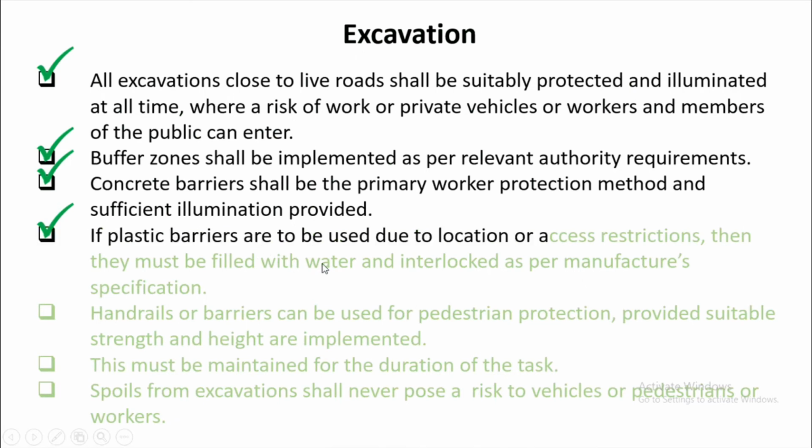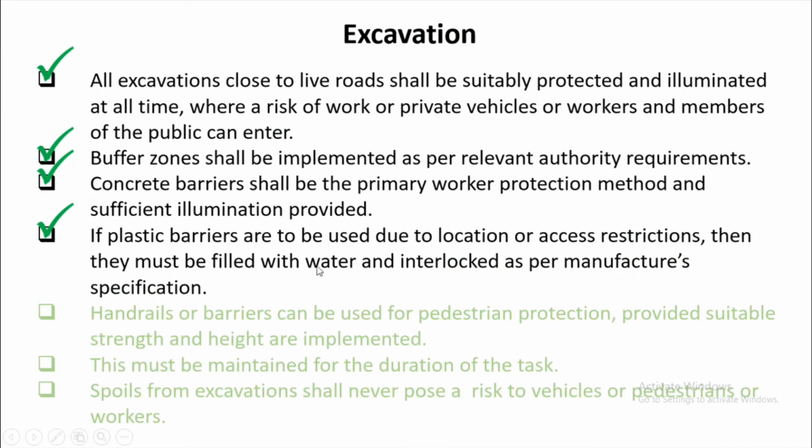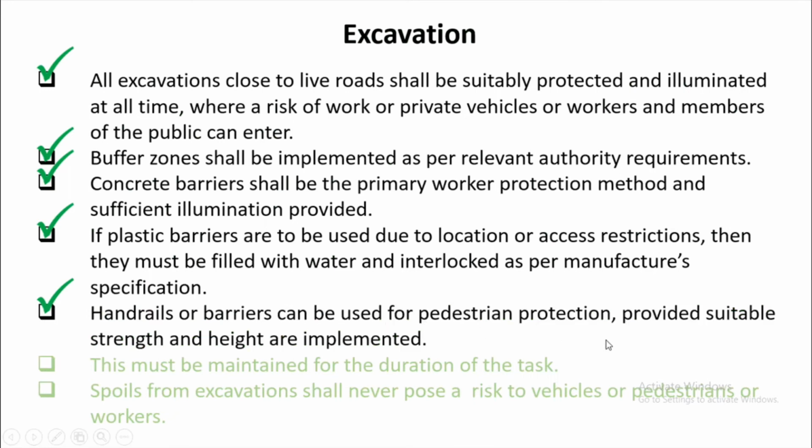If plastic barriers are to be used due to location or access restrictions, then they must be filled with water and interlocked with each other as per manufacturer's specifications. Handrails or barriers can be used for pedestrian protection, provided suitable strength and height are implemented. This must be maintained for the duration of the works.